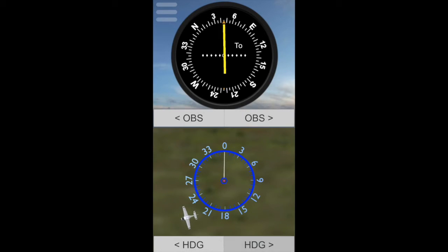Turning the plane now. Let's say I'm flying now. I want to fly towards this VOR. Here we go. I'm going to face 045. Fly straight ahead. I'm going to fly towards the VOR station. Very important concepts to grasp. Your heading does not affect the indication you get on the top. What matters is which radial the plane currently lies on at the moment. And that's how you get the indication you're looking for.